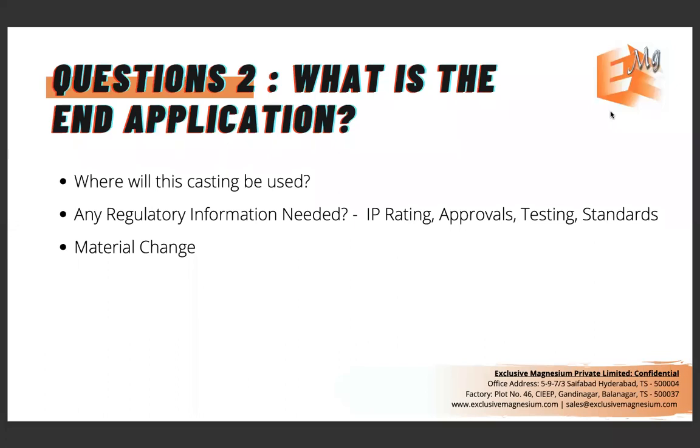So at a later point, you should not realize that, okay, you made it out of sand casting, but actually a rolled plate would have made more sense, or extrusion would have made more sense. Those kind of decisions you will be able to make only when you have that conversation up front.